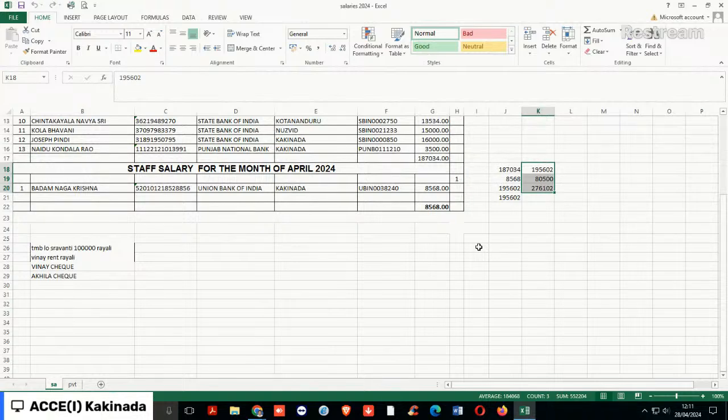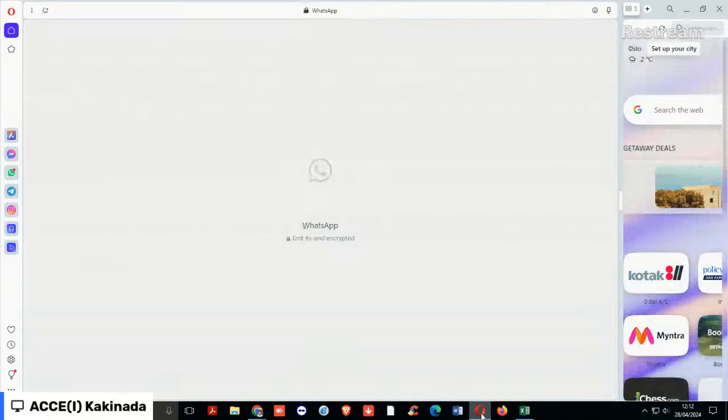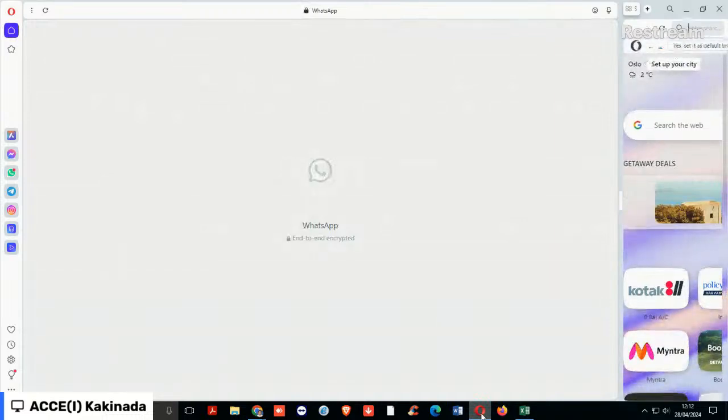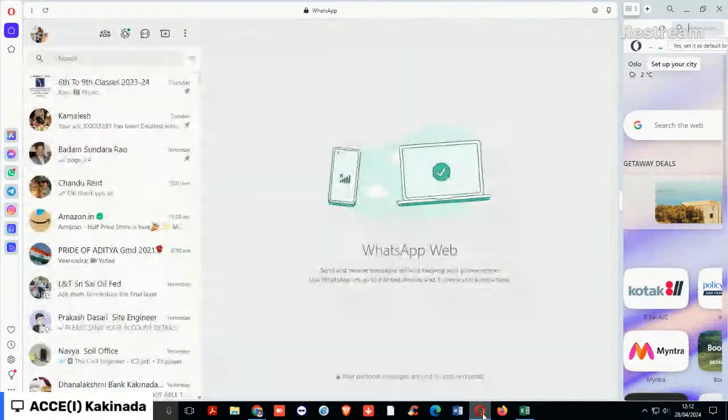There is a lot of greediness or stinginess on the part of the client, the designers, and the fabricators also. Providing these types of stirrups is almost useless. And such gaps should not be there after the fabrication of the stirrups. And these diamond rings should also be bent like this. This is almost a 45 degrees bend. A 90 degrees bend is also not permitted. It should be a 135 degrees bend at both ends, so that it is confined within the core concrete. That is one of the drawbacks, a mistake with respect to this slide.